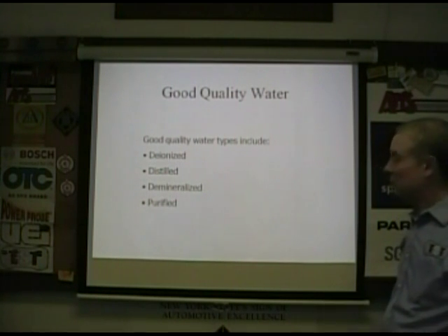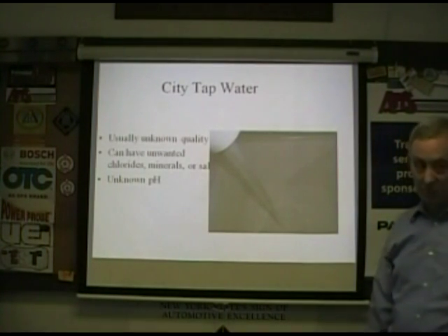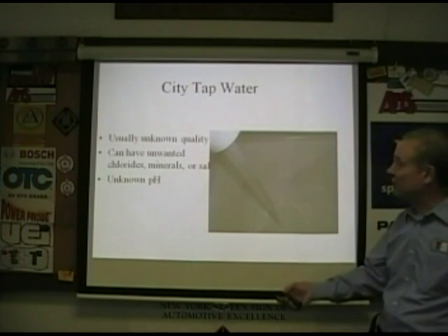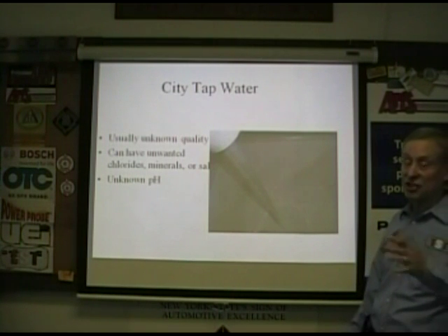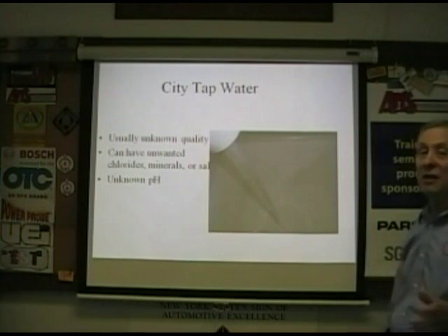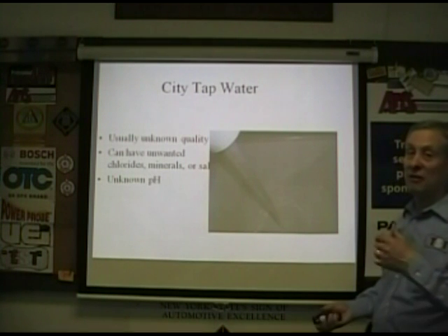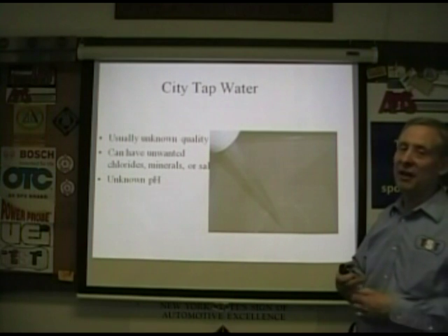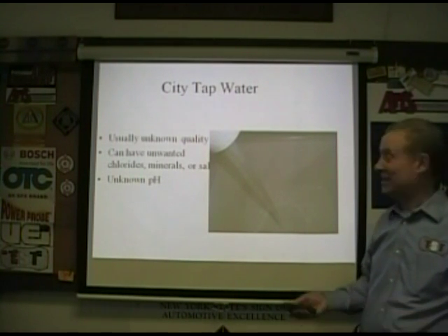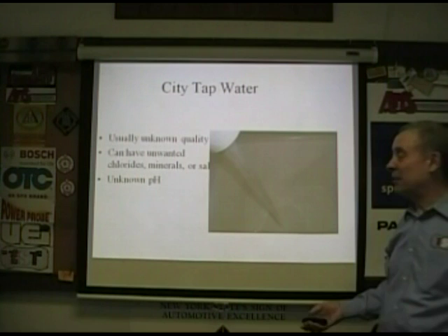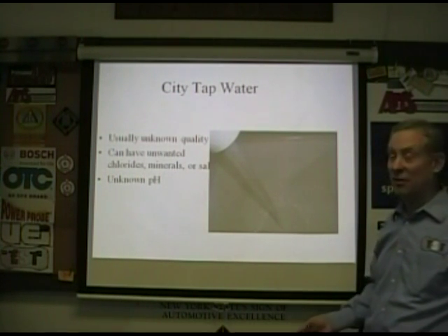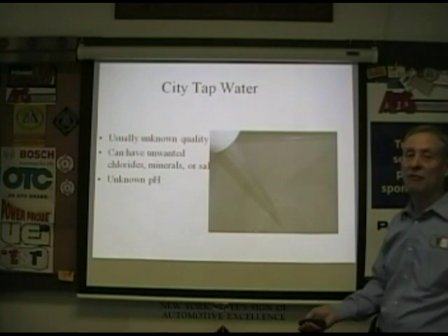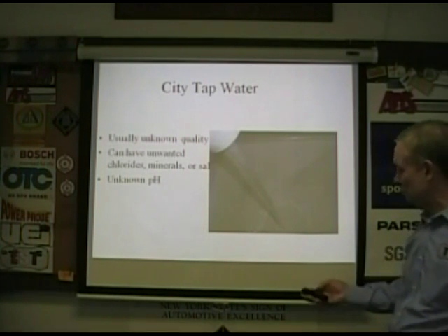Is this why some of the manufacturers are doing premix stuff nowadays? That's part of why they're using premix. It's a big part of it because there's all kinds of additives that get put into water. It's not just the water as it left the reservoir or the well. There's water treatment. You have chlorides, you have things that are put in to kill bacteria or to put the pH where they want it, but they might make a mistake, and it may not be compatible with antifreezes. Different manufacturers, this pH, something we don't really talk about much, but different manufacturers want different pHs in their coolants.